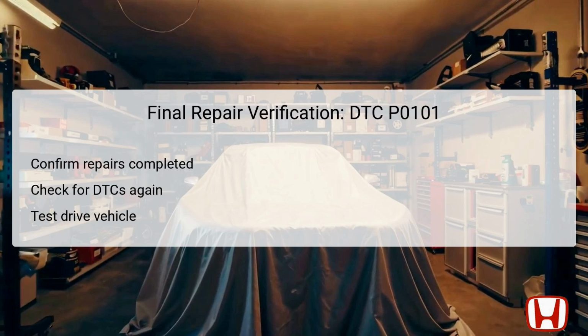Upon completing all necessary repairs associated with DTC P0101, it is vital to perform a final verification process. First, ensure that all the requisite repairs and components have been addressed thoroughly. Once confirmed, check for any stored or active DTCs by utilizing HDS to ascertain vehicle status.